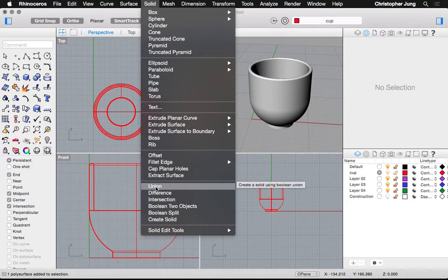If you have two beams crossing each other, it'll make an X. But if you use intersection, you have two beams, and it'll only pick that one little cube where the two areas intersect. But I recommend you guys just play around with it, because there's all kinds of different ways these commands work, more so than just my cut and dry explanations.